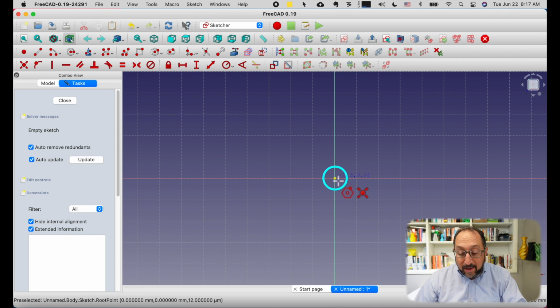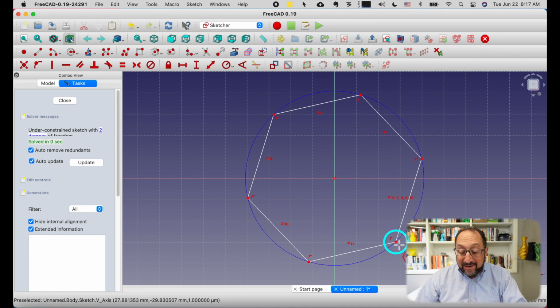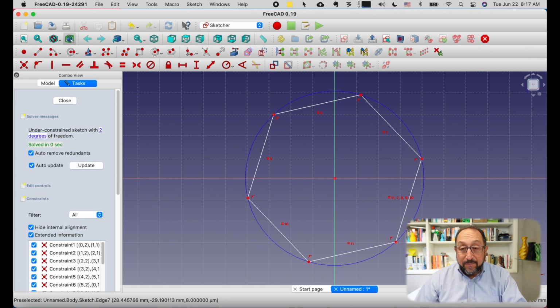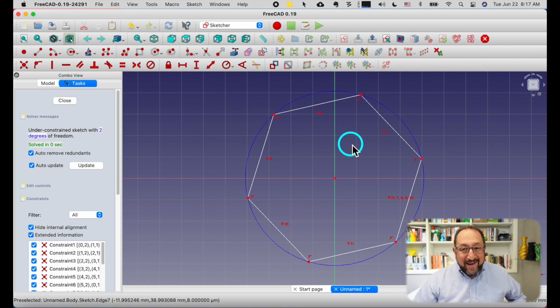object here. I'm going to hover over the origin until it turns white and drag out a polygon, and then left click a second time. So I dragged with the left click, I left clicked a second time, and then I'm going to right click to release that tool. Now, I don't want my text to be on an angle. I want it to be relative to a straight polygon.